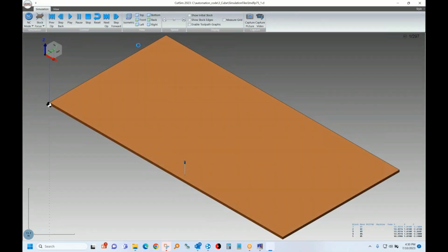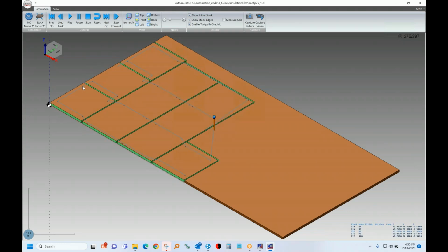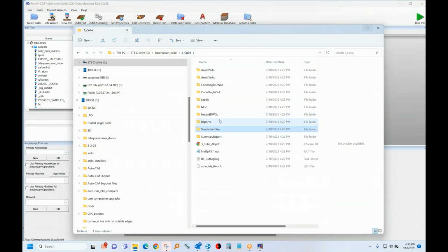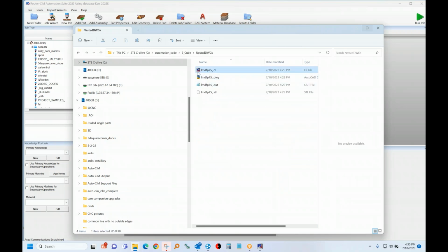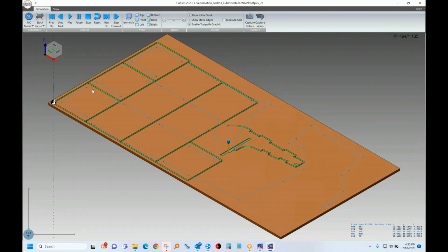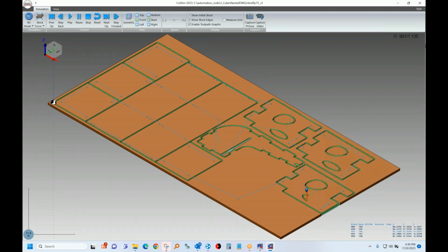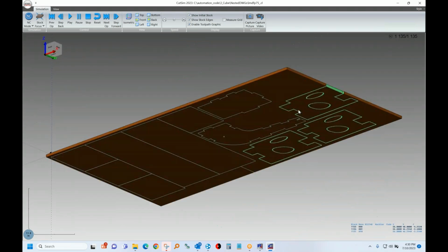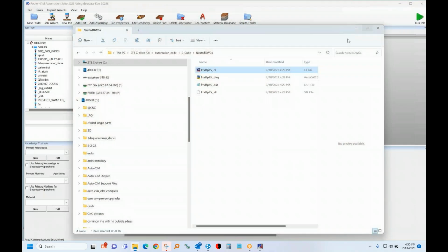This is before we did the modification. So this will show the toolpath before we edited the results. It shows the drilling happening first in a closest point order, and there's that stay down nest where the tool stays down and cuts from part to part without lifting up. I can also see the results after we edited the nest as well. So you have both of those, and you can pan and tilt and zoom while it's running those as well.